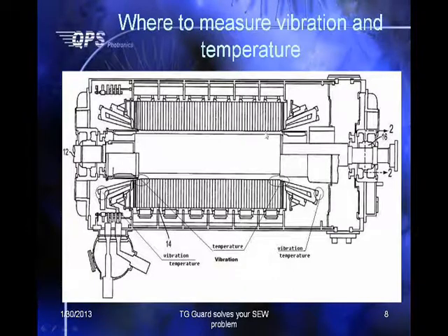Now you also come to understand why the sensor has to be placed here. Because the gap is so small, there is no room for you to place the sensor there. Another thing you want to avoid is to obstruct the hydrogen gas flow, which acts as the main cooling mechanism. Most of the time the cooling gas is fed from the center of the stator structure and flows outwards.